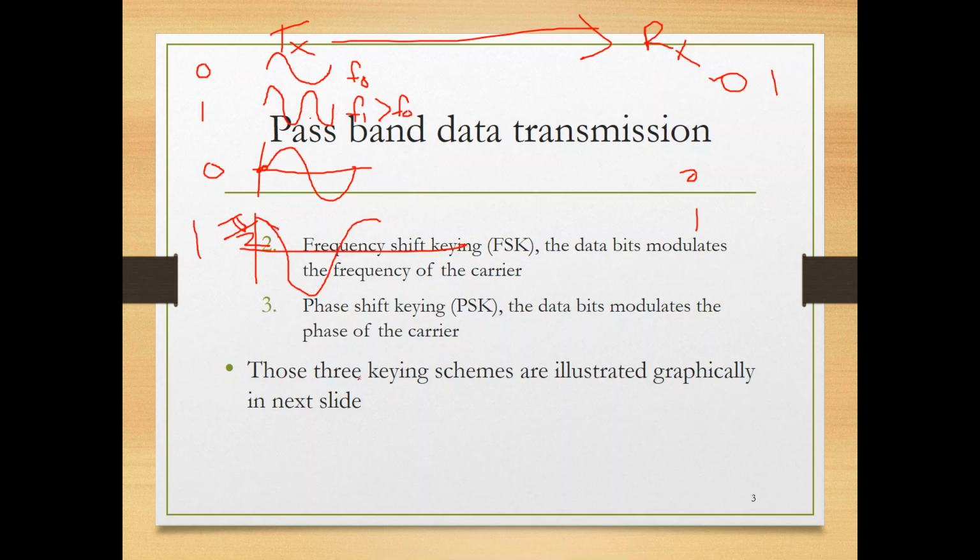For example, suppose that your channel is full of noise, full of interference. Which modulation do you use, amplitude modulation or frequency? Full of noise and interference. What happens to the interference? Think with me. If you are sending an amplitude modulated signal, then your signal is something like this. What if there is interference here? Your amplitude will become like this. So the receiver cannot distinguish this from this, because its amplitude is sensitive to interference.